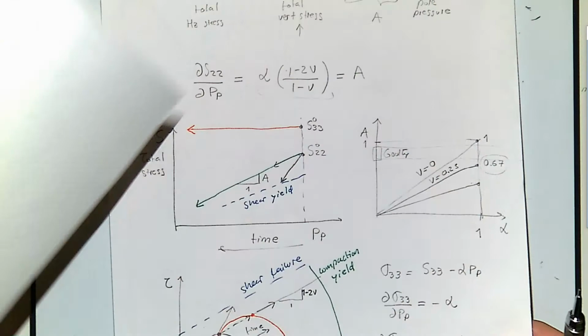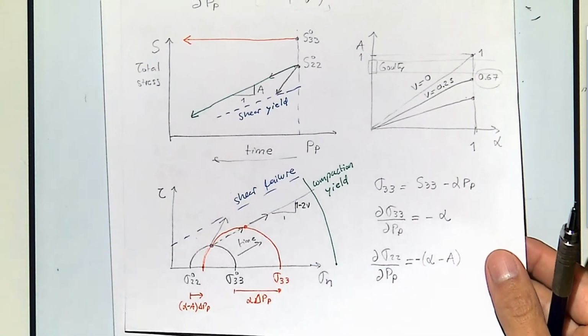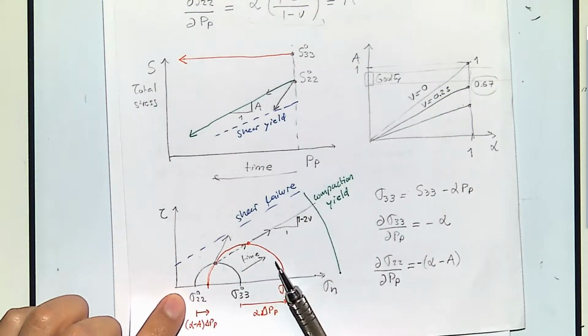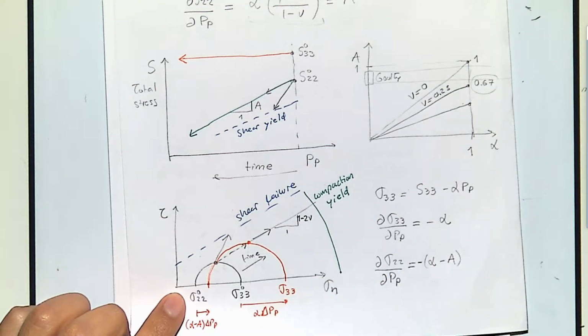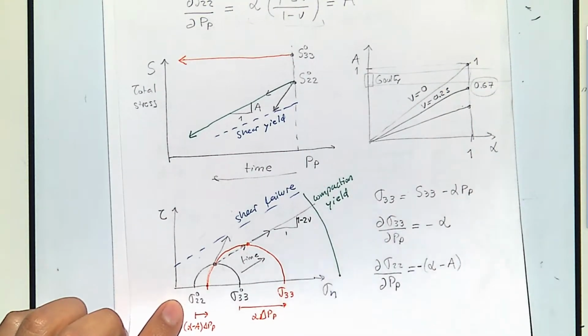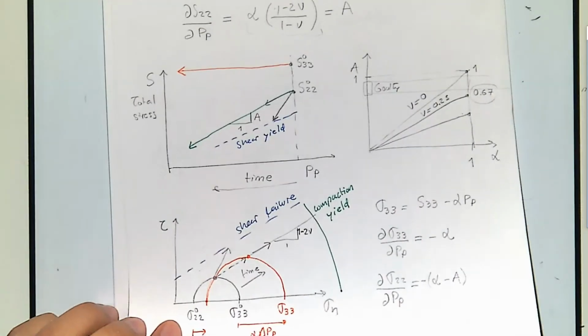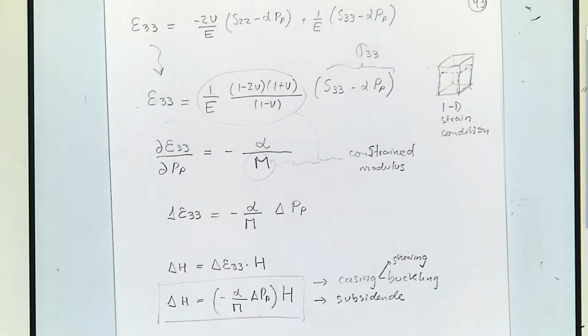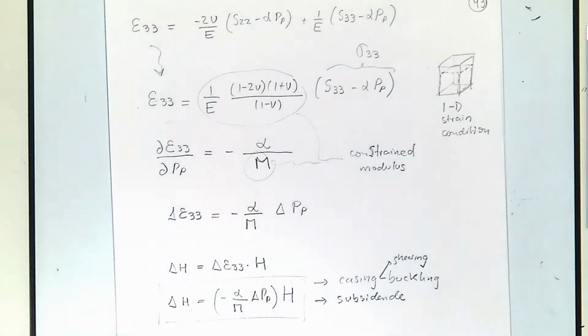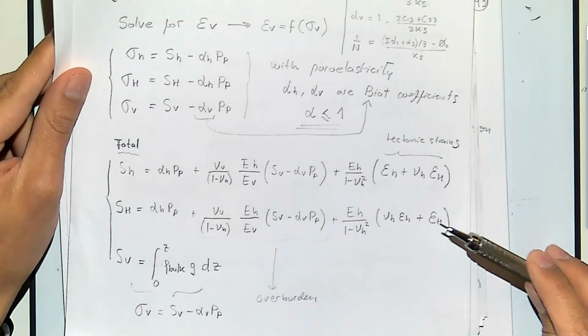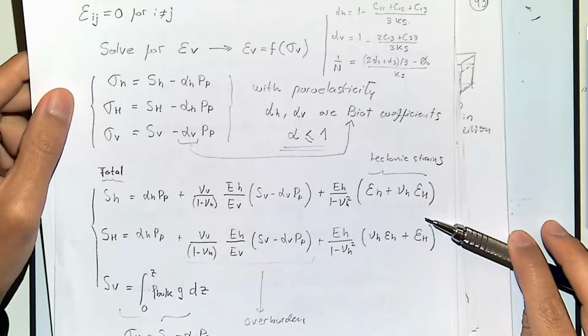And as a result, some of these stress paths and some of these parameters also are going to be anisotropic. So they are going to vary a little bit from what we have in the isotropic version. One more thing to add over here is that these equations that I just showed, let me find them again, are assuming, and this is going to be the connection with the next thing we're going to see, is this assuming a drained or an undrained problem?